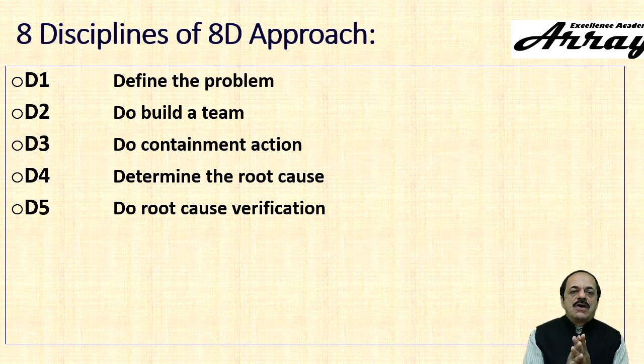Also, as you do the root cause verification and finalize, you should check in the FMEA, failure mode and effects analysis, why this was not entered there as one of the failure modes. If not, make arrangements to enter it in the FMEA so that the FMEA is complete, as well as if this FMEA is copy pasted for a similar item manufactured in future, that becomes a complete transfer of knowledge.